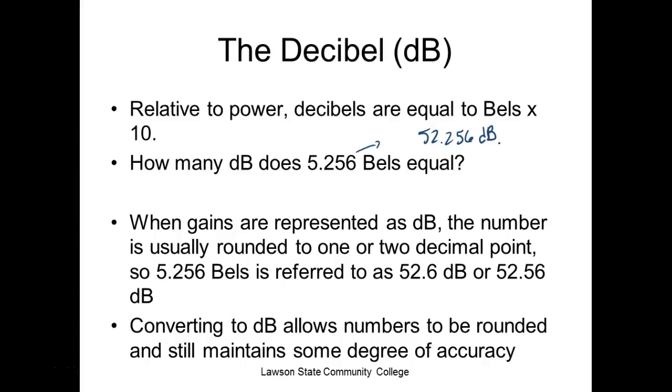Because everything that we talk about in electronics is approximations. Our resistors have tolerances. Our capacitors have tolerances. All of this has tolerances. Our wires have resistances, but it's also resistance per 1,000 feet, which means that it varies all over the place. And it's resistance at 20 degrees centigrade, which varies all the time. So again, there's no perfect. Our math is perfect, but our components are not.